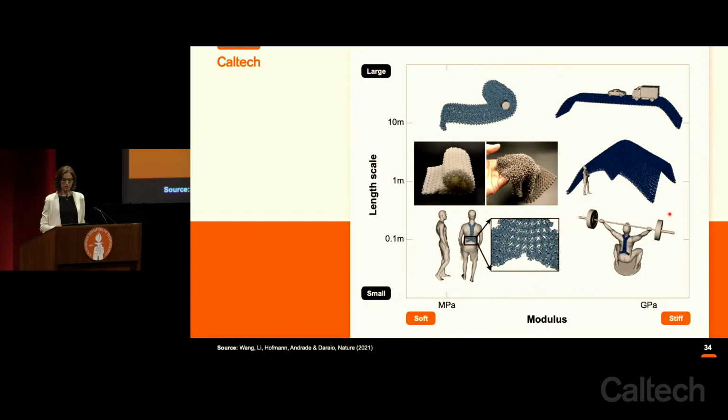We're also focusing on different materials. And so the two images you see here allow us to demonstrate the fact that these kinds of architectures can be produced with different technologies, with different manufacturing approaches, using different materials. On the left, you have nylon, which is, again, suitable for wearables. On the right is aluminum, for example, for stiffer supports. With the integration of alternative methods for confinement, which is not necessarily vacuum pressure, we're now exploring, for example, programming stiffness in the fabric through additional methods like electrical, magnetic, or thermal controls.